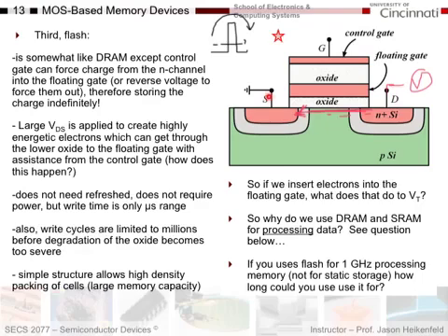The nice thing about this is once I've trapped this charge in here, it's stuck here, and so I don't need to refresh this thing. I can write this typically in only a time of about a microsecond. And so you've got a way to basically make a storage device where it will hold the memory indefinitely, and then when you want to read it out, you basically put your voltage on drain to source, and you see how much current you get for a given gate voltage. You don't have to erase this in the process, and it'll tell you whether or not you had charge there or not, and whether or not it was basically a flash bit that was in a 1 or a 0 state.